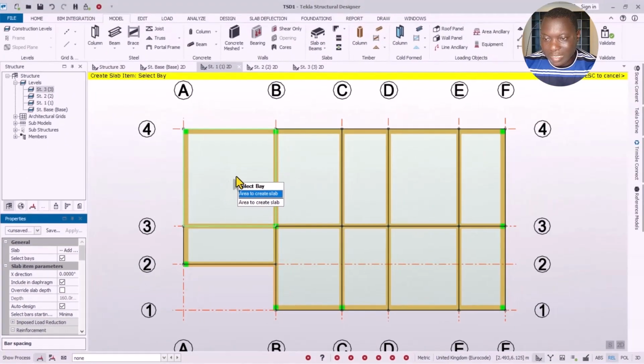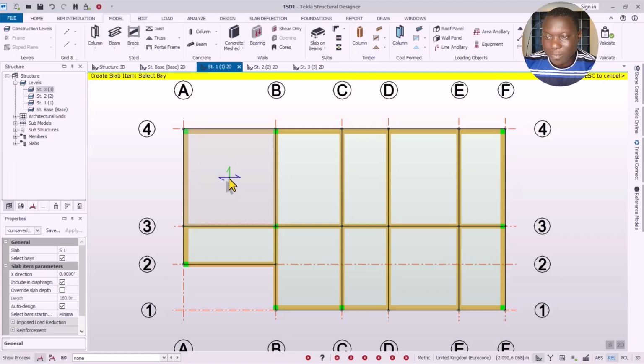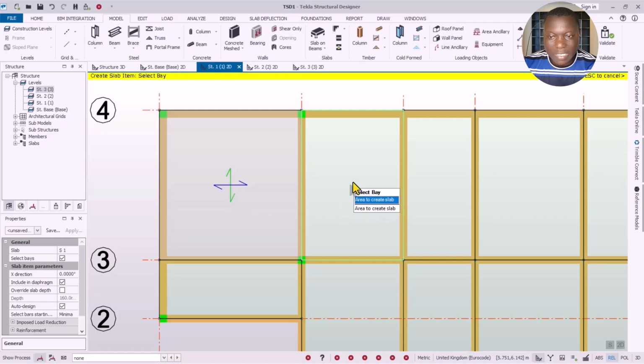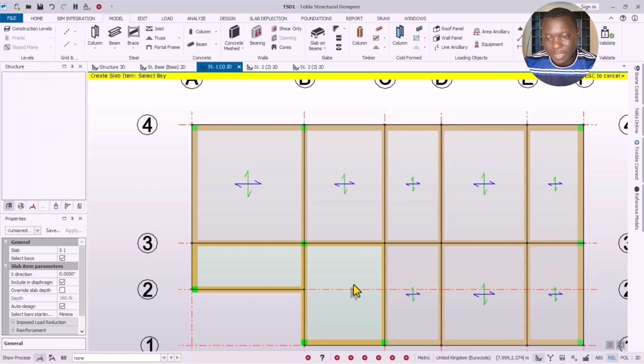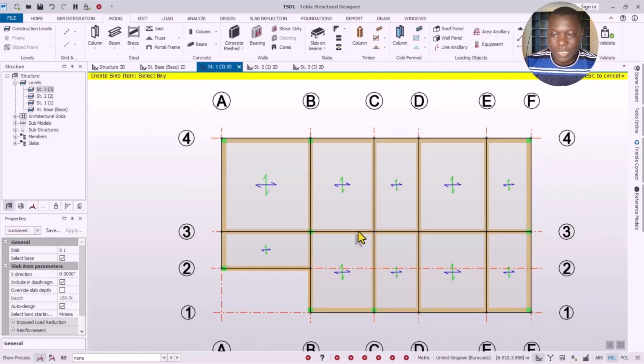So now you put your hand in the area bounded by the beams right here, click, and then to have the slab inserted just like this. This two-way slab, you can see two-way slab. So select and keep selecting in this provision. This is a staircase provision, I will add in a first concrete slab. Okay, so this is going to actually represent the inclined stairs reinforced concrete element. Okay, so I continue to place just like this. All right, so we have successfully placed our reinforced concrete slab on this floor.